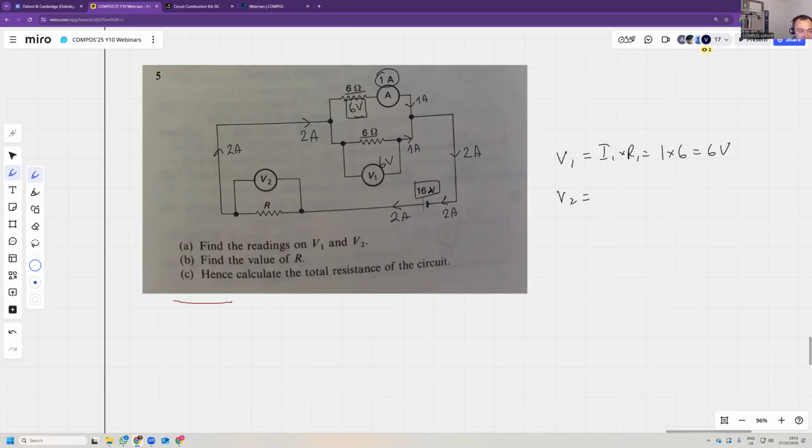So imagine you're trying to go around the circuit. So you get 16, so your potential here is plus 16 volts. You lose some of that energy here, and then you lose some of the energy here. So here you end up with 0 volts. And you know that it's 6 volts here, so this must be 6 volts. So the potential difference here is 10 volts.